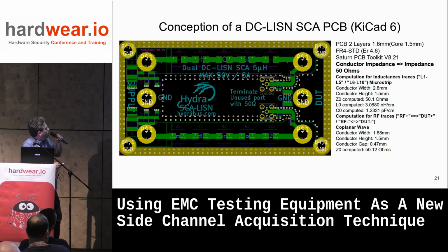And we try to match this PCB with Saturn PCB Toolkit, which is a free tool also, which allows you to compute the impedance to have 50 ohm. So you can compute the conductor widths there and there, depending on the path. This path or this path is for the spectrum analyzer there. You connect on plus or minus.